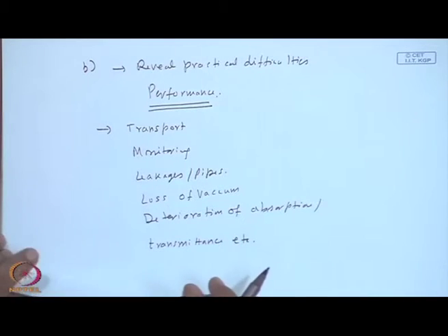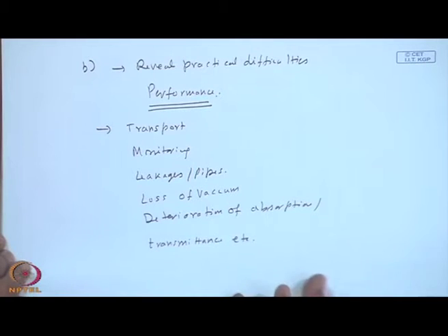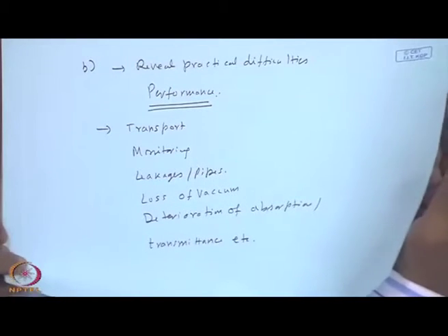For example, if you have got a black painted surface with tube and fin type of absorbers, which we have discussed in detail, it may so happen over a period of 6 months or 8 months, the black paint may peel off or may not have the same absorption that we have had at the beginning. Similarly, the transmittance, though not of the glass covers, particularly if plastics are used, they are not UV stable. Consequently, your transmittance deteriorates as time proceeds.